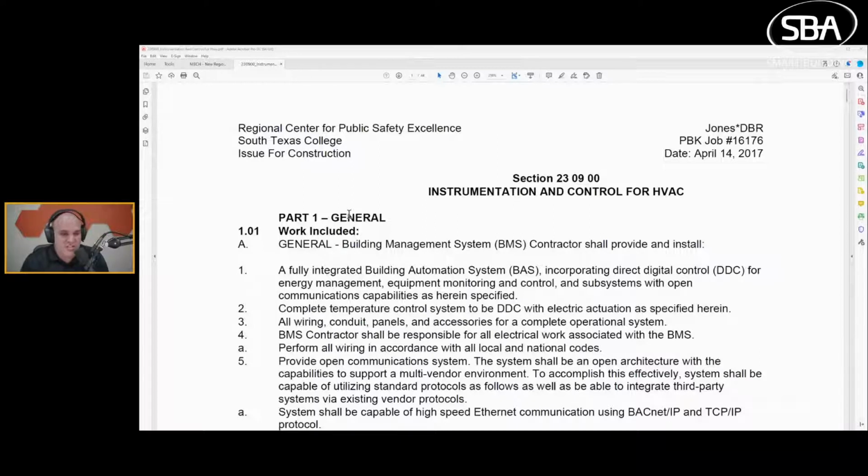Those are going to be things like our statuses, anything that is dry, so it's not wet, so it doesn't have electricity flowing across it. We're going to have resistive inputs. The big difference between resistive and dry is that resistive has that 5-volt DC signal typically going across it, and then you're measuring the resistance. Sometimes that's not how everybody's resistive inputs work, but those are going to be typically for our thermostats, 1K nickel, 10K type 2, stuff like that.